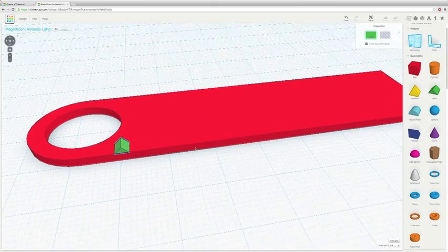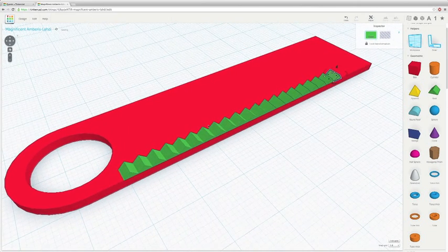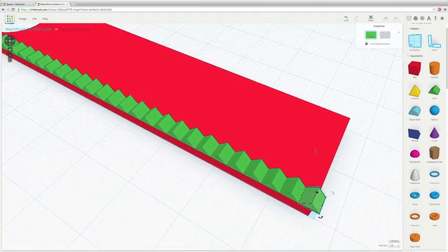Alright, that looks pretty cool. And now I'm going to hit Command D or Control D on Windows to duplicate the object. It glowed yellow for a second to let me know that. Alright, and if I move it and continuously press Command D, it will apply the same transformation of the last copy. So I've moved it, and I'm just going down the line. One more. Okay, I got it.